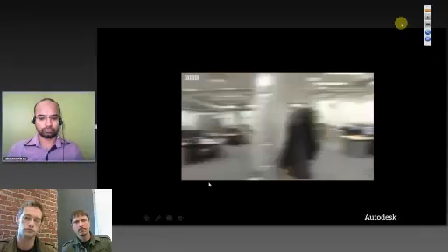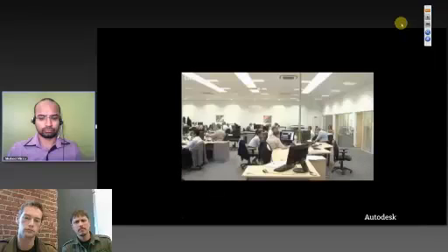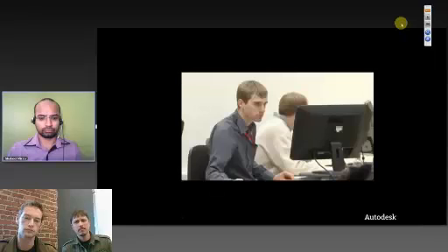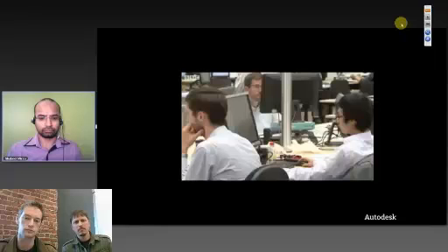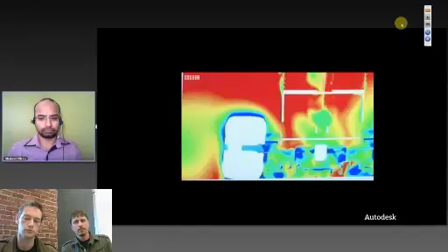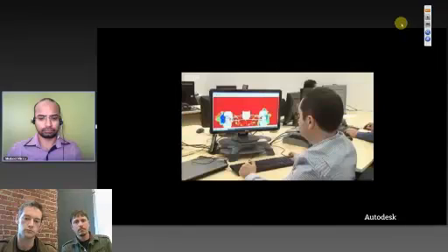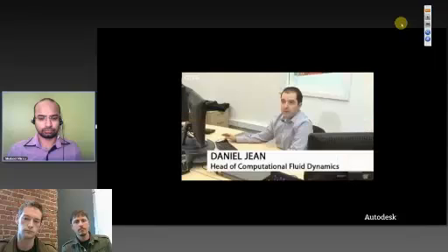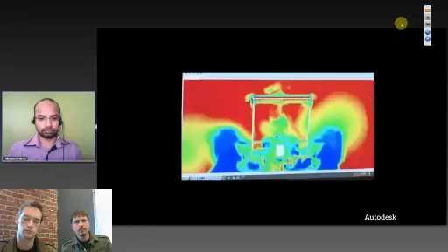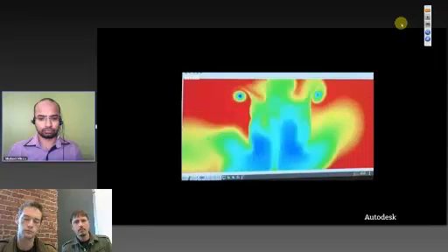Really, a lot of our performance comes from aerodynamics. So that's one of our larger departments with around 40 people in it. One of the ways we try and both shortcut our time to market and to improve our performance is to use CFD. Now, CFD is computational fluid dynamics. It's effectively a digital wind tunnel. One big difference between the CFD and the wind tunnel is that we have the power to visualize flow and what it's doing. We break the car down into around 300 million cells, and we solve the equations that govern the airflow around the car to each one of those cells.